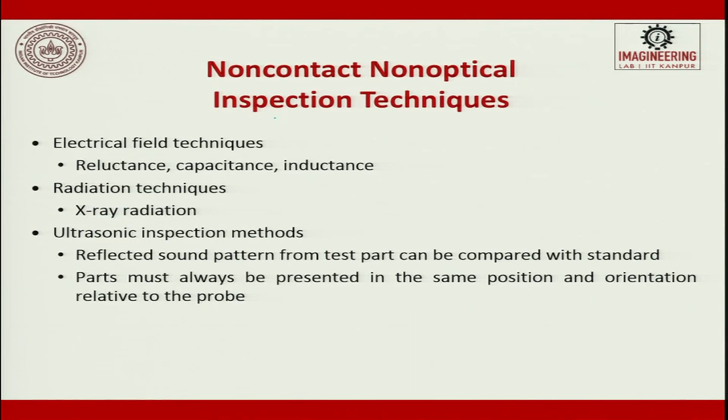For non-contact, non-optical imaging techniques, we can use electrical field techniques such as reluctance, capacitance, inductance. X-ray techniques are used, and ultrasonics are used today to measure the dimensions. The reflected sound pattern from the test part can be compared with the standard, or the part must always be present in the same position and orientation relative to the probe. We can use ultrasonic techniques for imaging. So, today we use all the three, capacitance based, inductance based, X-ray and ultrasonic for imaging.